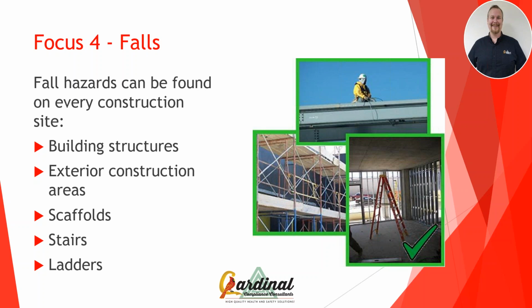We have to build scaffolding on most projects so that we can have a safe place to walk to work. Now think about that. We have scaffold builders putting up scaffolding. If you've ever watched a scaffold builder, it's amazing the effort they have to put into using fall protection to protect themselves. Because think about it, as you're building that scaffolding, you don't have a stable place to stand. You really have limited options on where you can tie off, where you can connect your fall protection. And this trade is working this way to try to provide other construction workers a safe place to work.